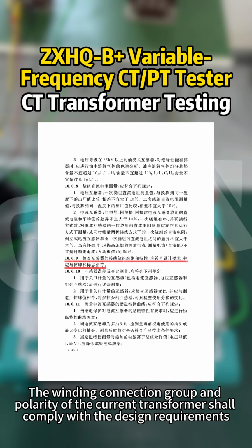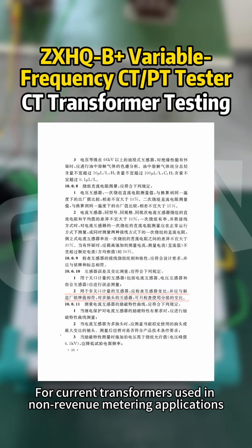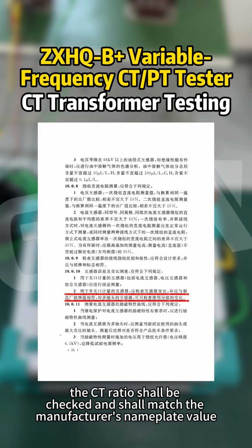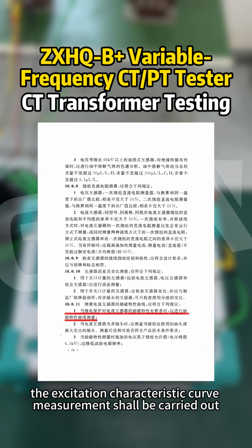The winding connection group and polarity of the current transformer shall comply with the design requirements. They shall also be consistent with the nameplate and markings. For current transformers used in non-revenue metering applications, the CT ratio shall be checked and shall match the manufacturer's nameplate value. When required by the protection system, the excitation characteristic curve measurement shall be carried out.